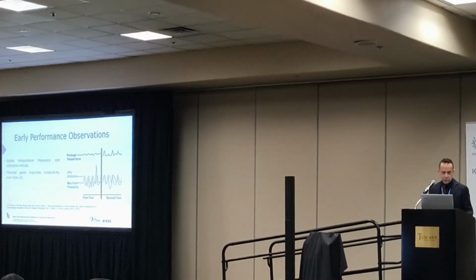With the new CPU that we installed, we did one more test. We applied new thermal materials, actually phase change thermal materials, on the CPU. And we did one test using Intel software, which measures temperature, CPU utilization, and max core frequency. And we performed the same test again after a couple of days of usage, when the CPU went through some thermal cycles. So the phase change material started to be applied, let's say, better.